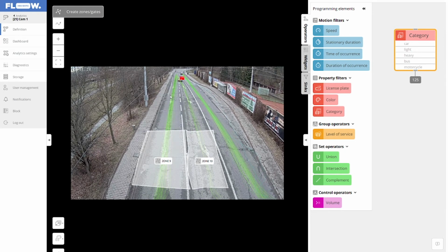This is approximately 70 meters far away from the stop line, and it will be useful for detecting vehicles that are approaching the intersection, and in case you have, for example, total red during the night on the intersection, it can detect the car and send the controller information enough in advance so you can turn the green for this specified vehicle.